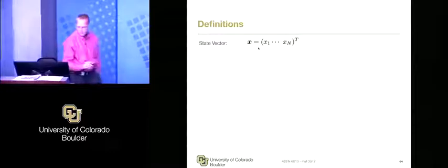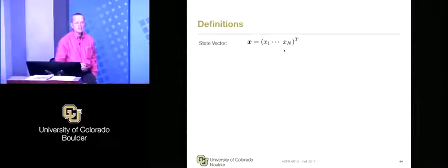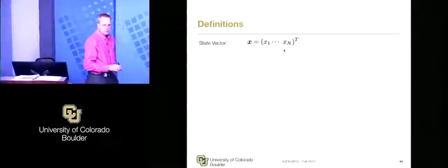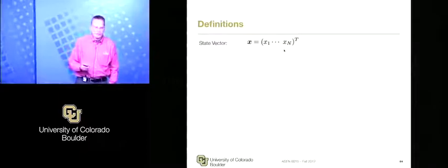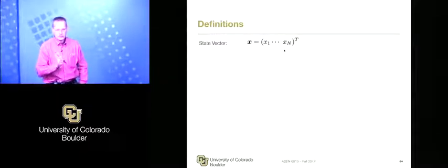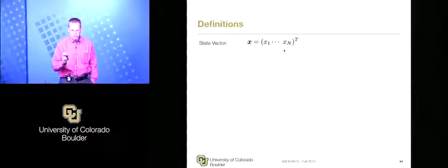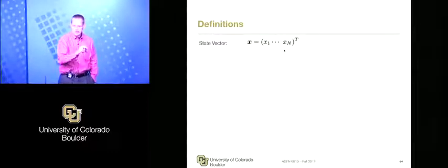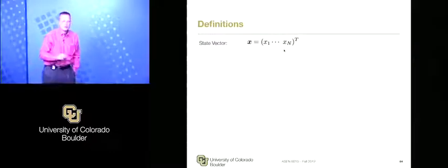For attitude, or for the complete... So this all comes down to what is this n, right? How many do we need for a system? Let's start out simple with the spring mass damper system. What is the n that you need? What's the size of that state vector? 2, right? It's a second order differential equation, so I have to track x and x dot. It's driven by x double dot.